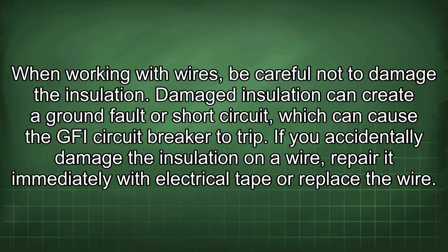When working with wires, be careful not to damage the insulation. Damaged insulation can create a ground fault or short circuit, which can cause the GFI circuit breaker to trip. If you accidentally damage the insulation on a wire, repair it immediately with electrical tape or replace the wire.